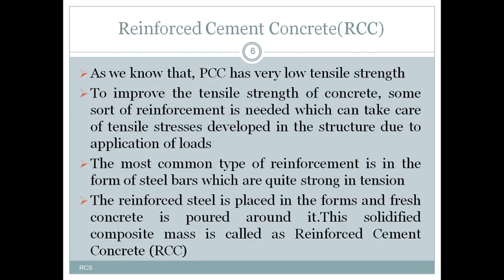Next, we'll discuss reinforced concrete. Why did reinforced cement concrete come into existence? As we have a problem with PCC, that is, PCC has very low tensile strength. To improve the tensile strength of concrete, some sort of reinforcement is needed which can take care of tensile stresses developed in the structure due to applied loads. The most common type of reinforcement is in the form of steel bars, which are quite strong in tension.